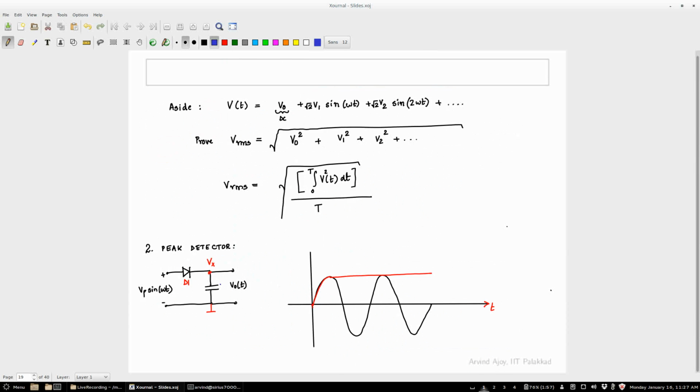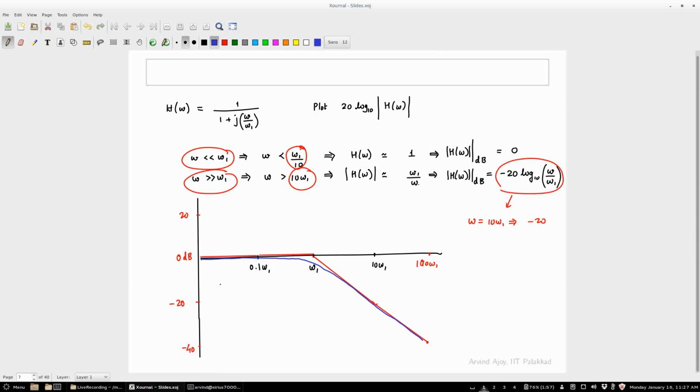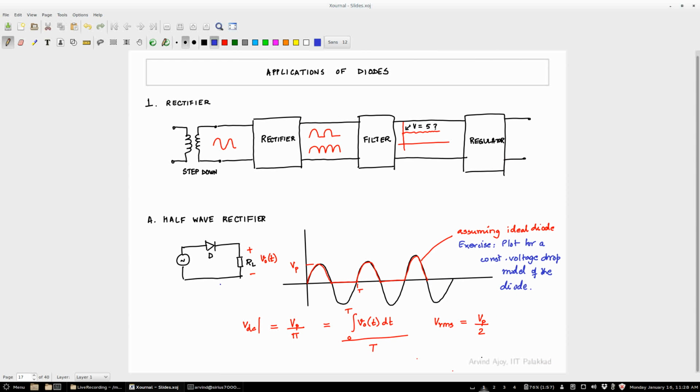Okay. So now you want to connect your load. The load will be disconnected from here, right? I don't want to connect the load here. You have the capacitor, then after the capacitor you take the regulator, and then you put the load. That's the small change that you will have.